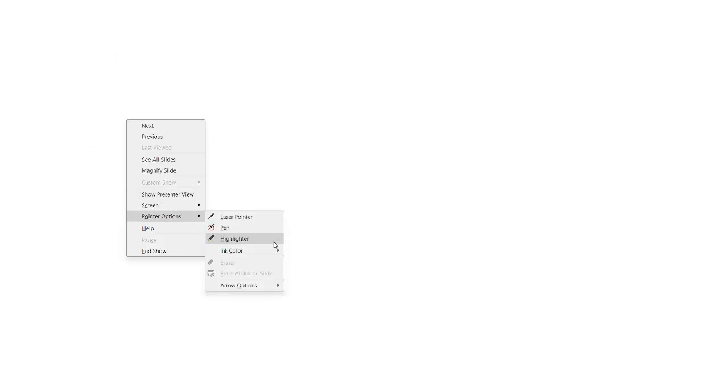The test bench I will tell you afterward. But for the AND gate or any adder circuit, first you need to design, and then to verify whether your design is working properly or not, you need to write the test bench.